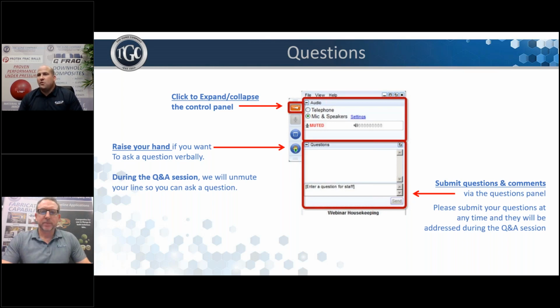Typically, if you had a convolute tube and a filament wound tube side by side, with the same angles, the convolute tube would allow for probably a little bit better property performance with ILSS and also compressive strength. I think with filament wound tubes, you can manipulate the angles to get pretty close to convolute tubes. But typically, if you did it side by side, your convolute would give you a little bit better mechanical performance. Yeah, I would tend to agree. You can get very, very close with filament winding to a convolute tube.